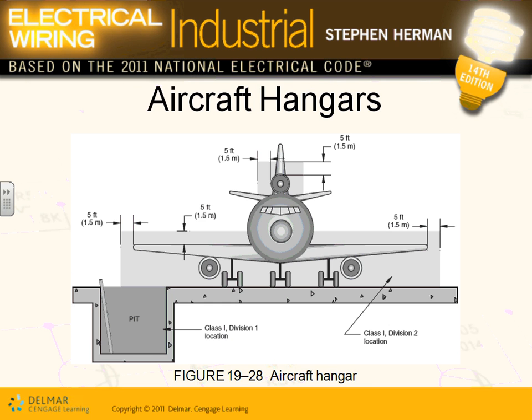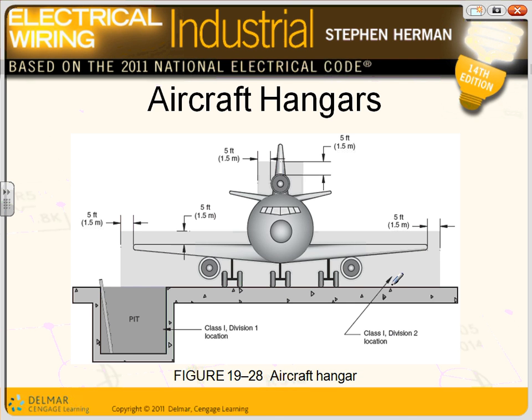You go to the aircraft hangar. So that's it, the whole article summarized in one page. Aircraft hangar, guys, same thing. In any area, if you have a pit, this is jet fuel. You have a lot of jet fuel, right? In the other ones, they have gasoline and fuel and so forth. This is Class 1 Div 1 for jet fuel in this area. That pit is Class 1 Div 1.